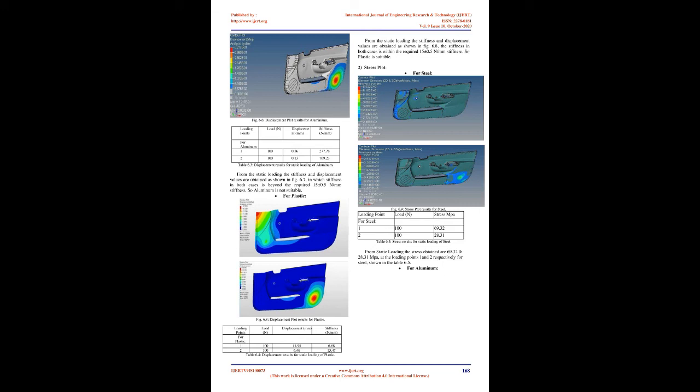5.6 Static analysis. The linear static analysis is applied to analyze displacements, strains, or stress of structures. This analysis is valid for linear static mechanical problems without geometric nonlinearity, contact, or material nonlinearity. Static nonlinear problems can be solved by nonlinear analysis, whereas transient problems are solved by other methods. The linear static analysis formulates structural equilibrium on the initial configuration without consideration of deformations. Hence, it is only valid for problems showing small displacements.